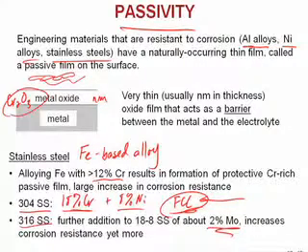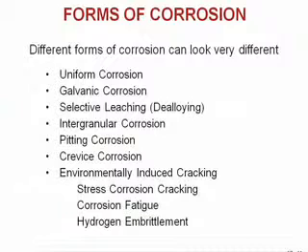We can add more molybdenum, more chromium. We can add tungsten, and in fact add more nickel and take away the iron. And we end up with extraordinarily corrosion-resistant materials. Nickel-based alloys with 25% chromium, 6% molybdenum. We have several percent tungsten. And these materials are protected by thin oxide layers on the surface, extraordinarily corrosion-resistant. You might even store nuclear waste in them for 100,000 years. Okay? Phenomenon of passivity is a critical part of corrosion.